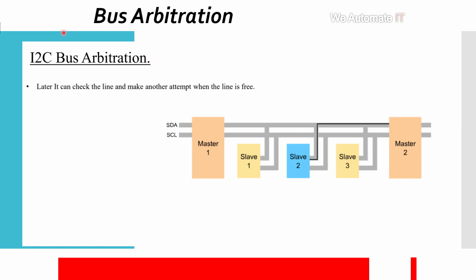So let's revise once again. I2C is a two-wire serial communication protocol that uses SDA for data and SCL for the clock. The communication is controlled by the master and received by slave devices. Each slave has a unique address. By the address, the master identifies which slave the message is for, and from there it gets the response. The data transfer follows start, address, acknowledgement, data, and stop, which is the process of doing the data transfers.